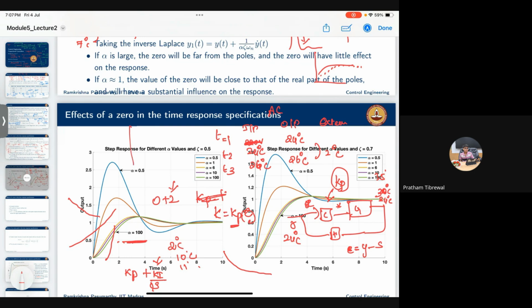The thing you're asking, see, if I'm doing like this, even if the error is 0.01, this integral controller will add this 0.01 forever. For a proportional controller, this doesn't matter. This is a very small error. But the integral controller will keep track of this, so it will add up.